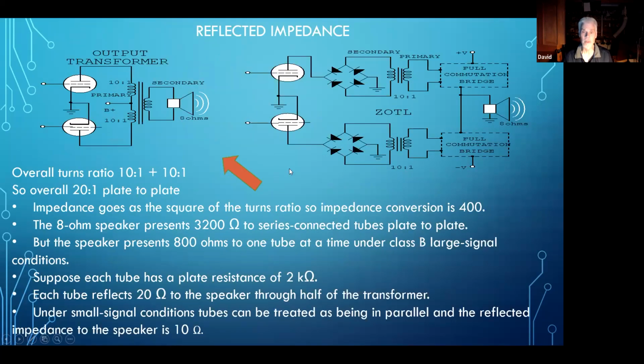Now, this is one of the most interesting, and this gets kind of technical too: reflected impedance. When you're considering an amplifier driving a speaker, the speaker is not a resistive load. It's complex.